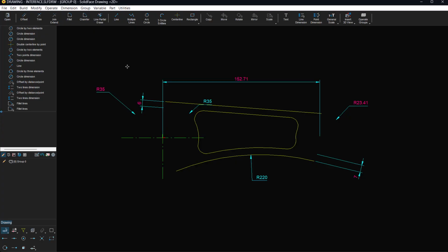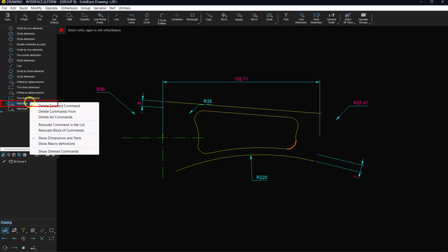The circle should have been separated at the tangency points before the fillet operation. At this point, we could continue and create an external arch. But let's undo the operation to return before the fillet operation. In the list of commands, select the first fillet and delete all operations after it.